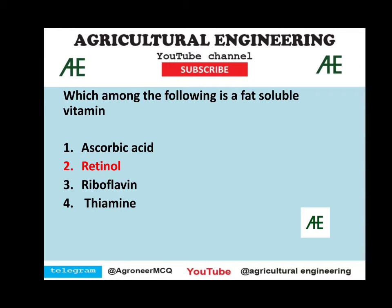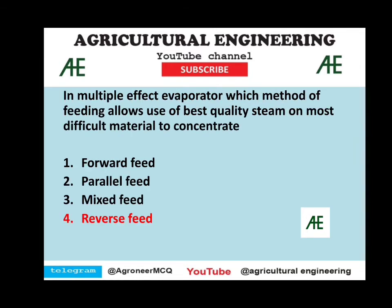Next question was, in multiple effect evaporator, which method of feeding allows use of best quality steam on most difficult material to concentrate? So the answer is reverse feed. Reverse feed multiple effect evaporator allows best quality steam on most difficult material to concentrate. In forward feed, the flow of our concentrate and the flow of steam is in the same direction. In reverse feed, they are in opposite direction.